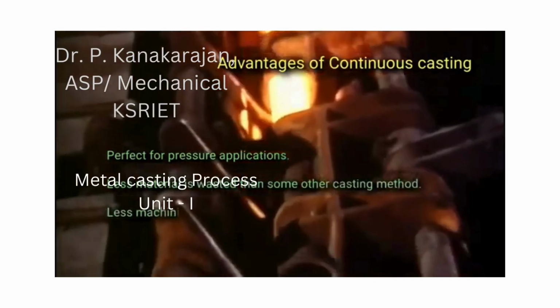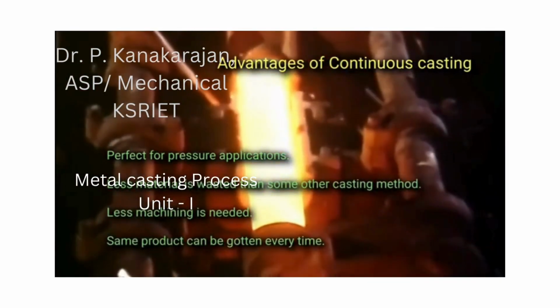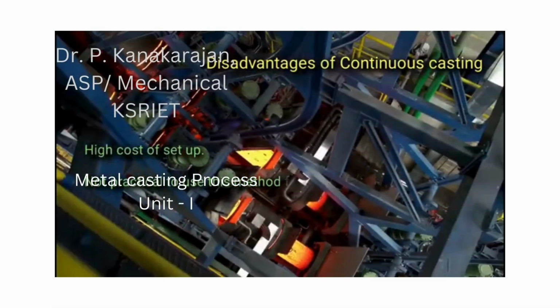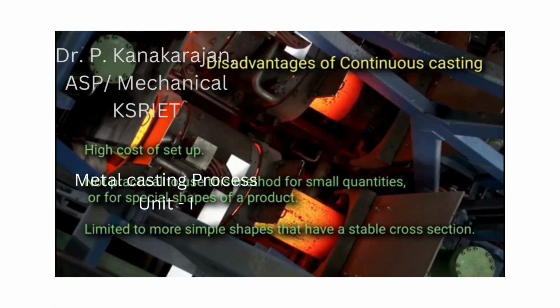Advantages of continuous casting. Perfect for pressure applications. Less material is wasted than some other casting methods. Less machining is needed. The same product can be obtained every time. Disadvantages of continuous casting. High cost of setup. Not practical to use this method for small quantities, or for special